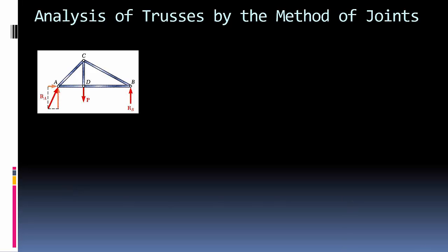Okay, now to the important stuff, the analysis of the truss. So there's two basic ways to analyze trusses. This first way that we're going to show you is the painful way, but it's important that you know it because, quite frankly, sometimes you have to do it. If you can avoid this method, avoid this method. This is a lot of work. It's not terribly hard. It's just a lot of steps, a lot of opportunities to make a little mistake here or there. But it is absolutely necessary for some things, and this is called the analysis of truss by the method of joints.